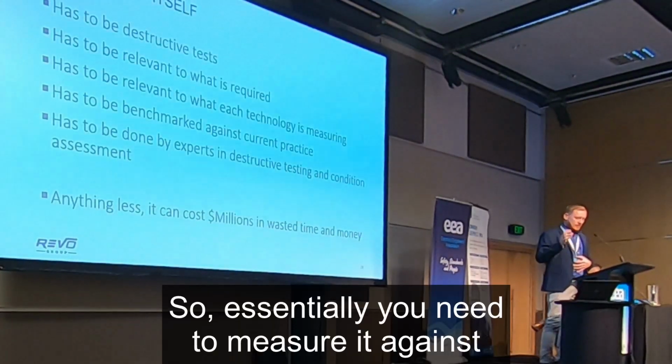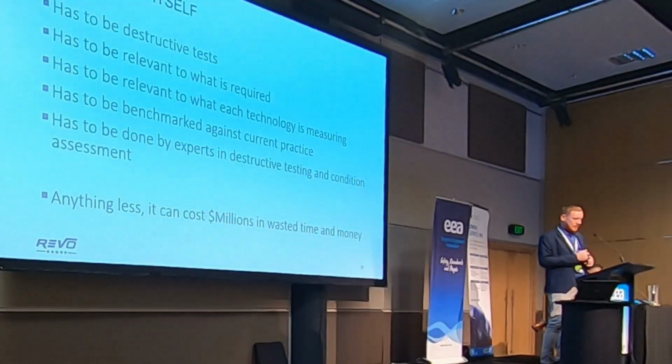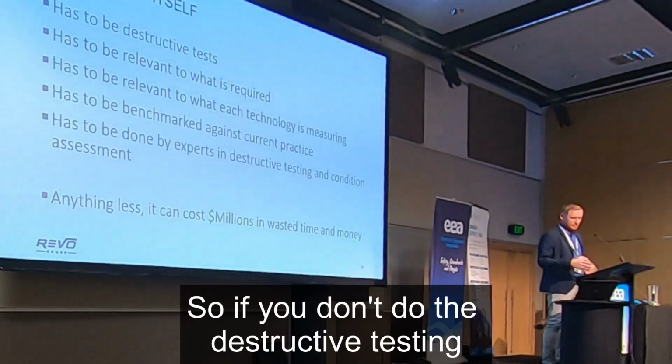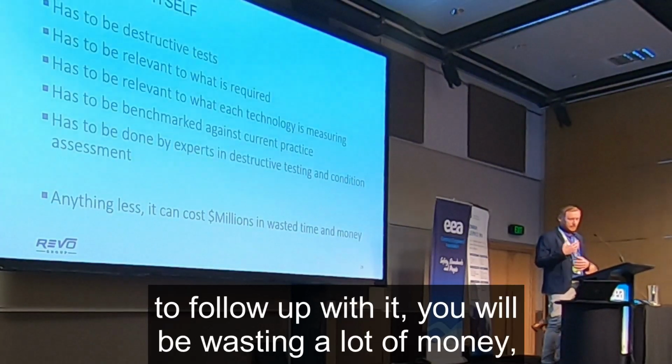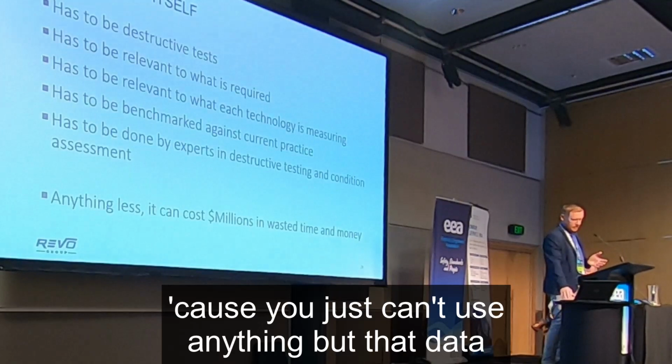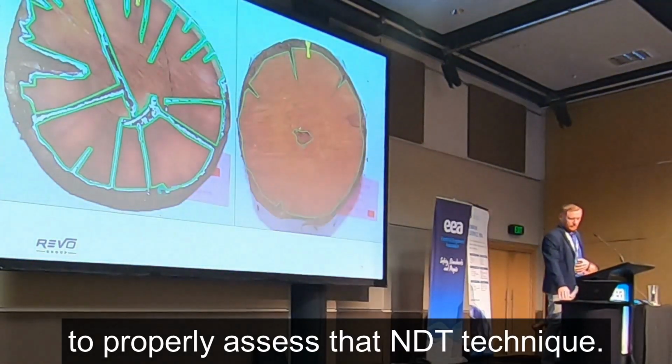So essentially, you need to measure against what that technology is actually measuring. So if you don't do the destructive testing to follow up with it, you will be wasting a lot of money. Okay? Because you can't use anything but that data to properly assess an NDT technique.